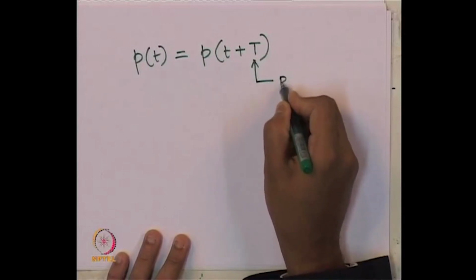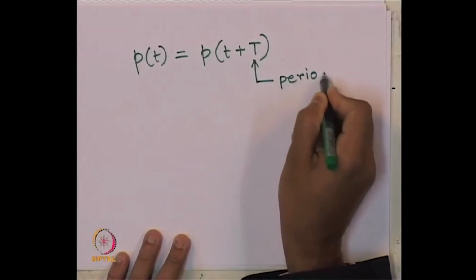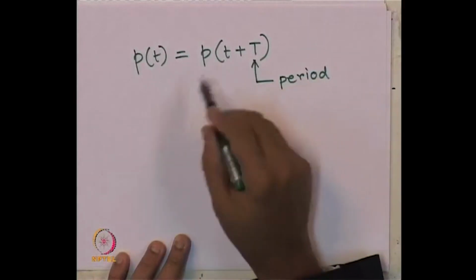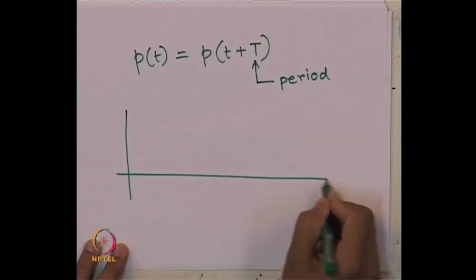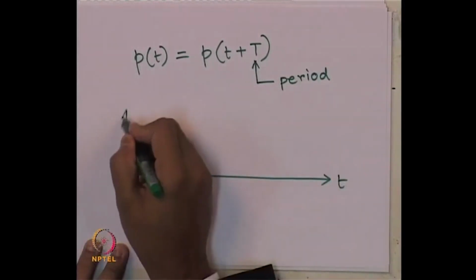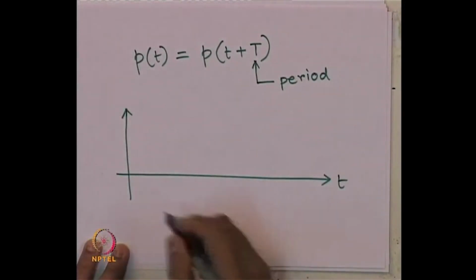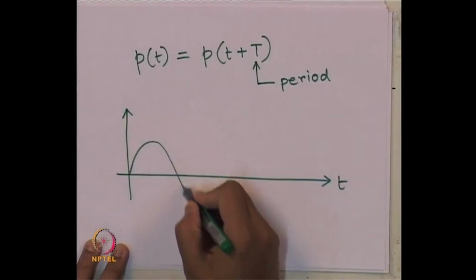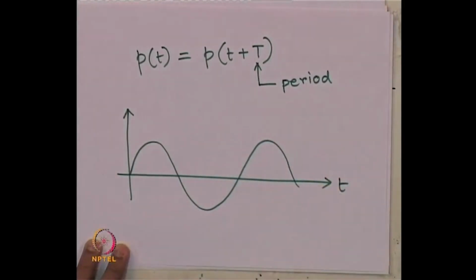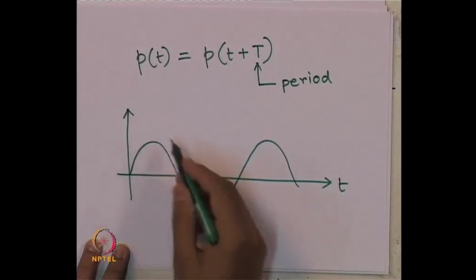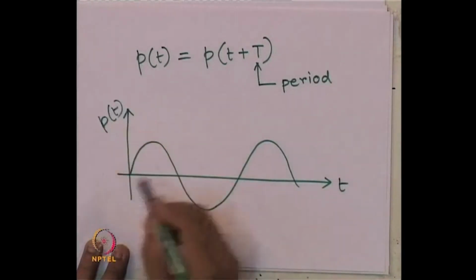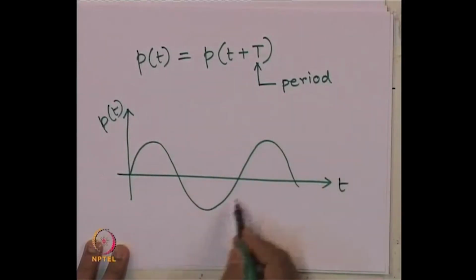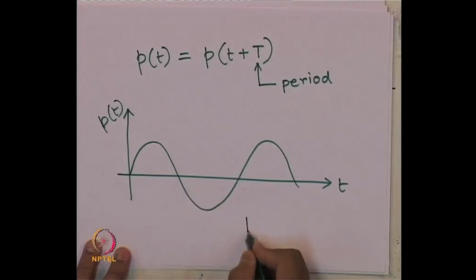So, this is the type of force on the system when the dynamic load is present. For example, it can be sine load or cosine load, where the nature of P of t is repeating after a certain period or certain time. In that case, it is called periodic forced vibration.